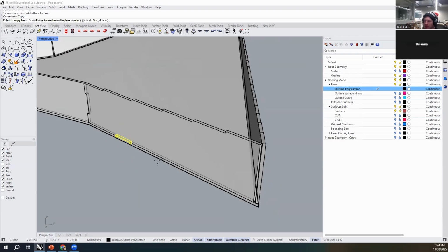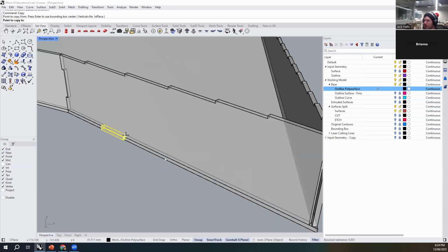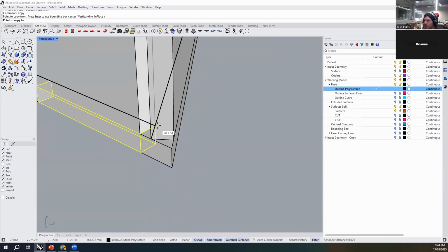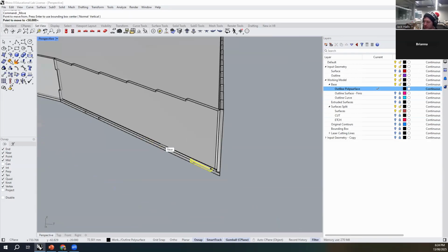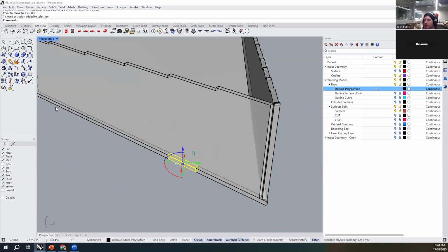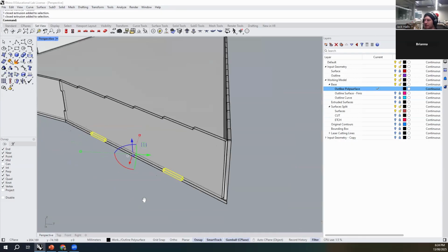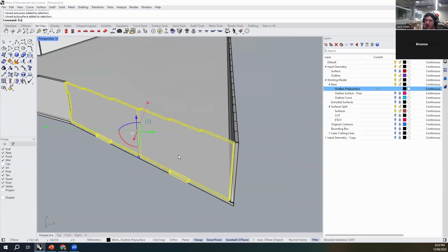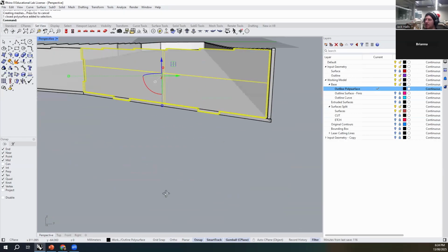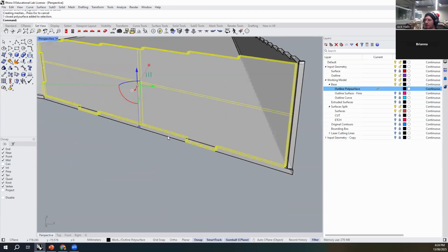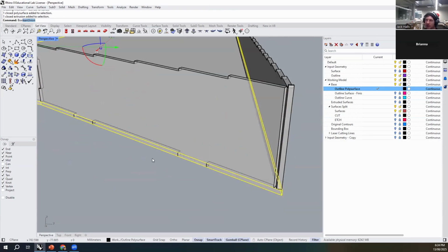And then you might say, okay, well, that's one. I'm going to do another one. I'm going to do 2 per piece, and I'm going to do the same 50 millimeters in that direction. Okay, so we've got 2 of these little notch friends here. We're going to go ahead and use our Boolean union, and you can see that's turned that into one piece, which is now intersecting with the base. And then I'm going to use my Boolean difference and select this as our cutting object.